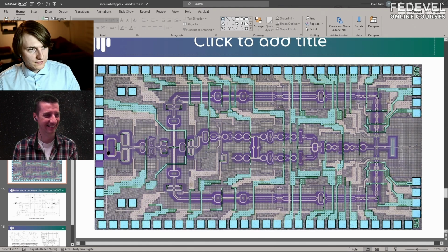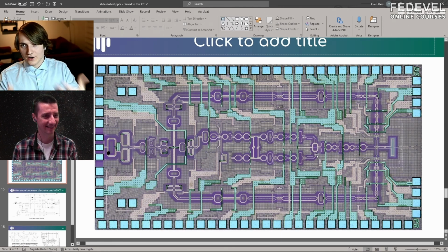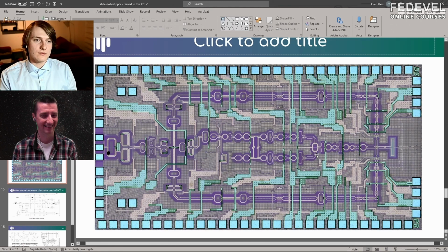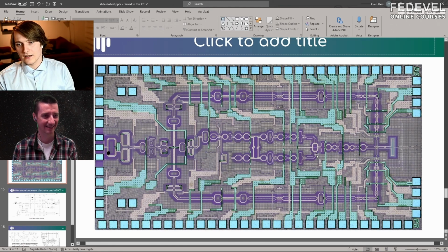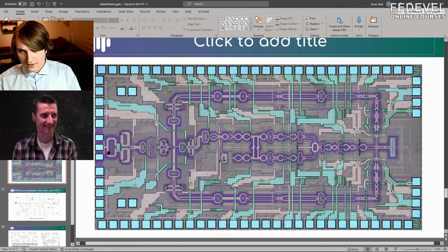If we do millimeter wave stuff, you can really see the millimeter wave structures, right? So these are transformers. We can make transformers on chip, and we use an EM simulator like ADS or HFSS to model them. And then we include that in our schematic simulation as an S parameter block. And then we can design this entire chip. And then you get it back from the foundry, and then you turn it on. You play a bit with the voltages, and then it works.